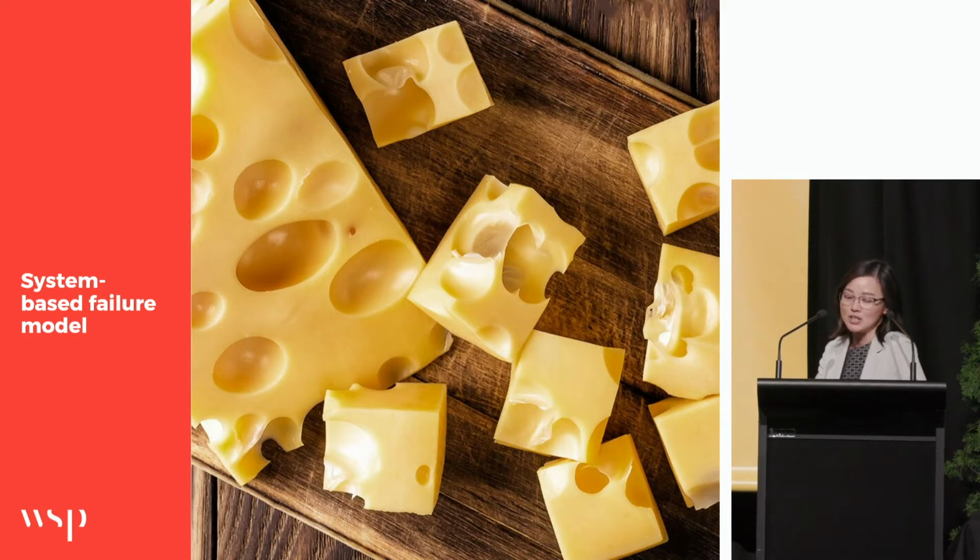So we imagine and we know our daily work is very heavily statistical and probabilistic, like material strength. Do we really know the characteristic strength of the material that we are designing? Definitely not really. We accept between the 5% and 95% percentile as characteristic strength. And also loading, seismic loading, wind loading, is all based on statistics.